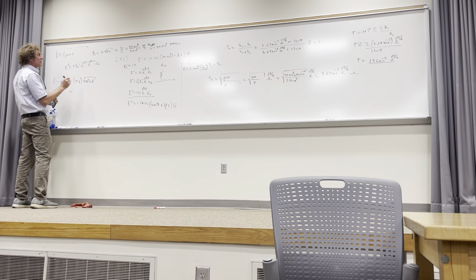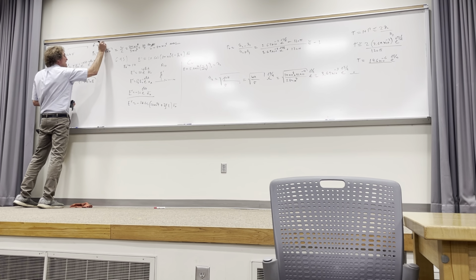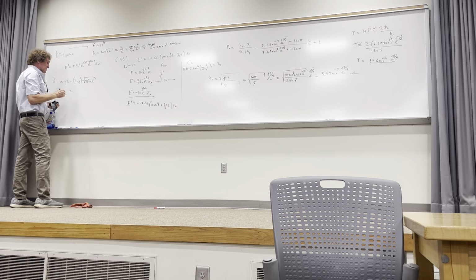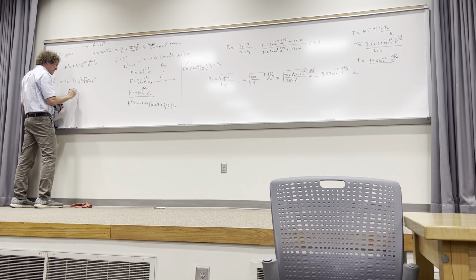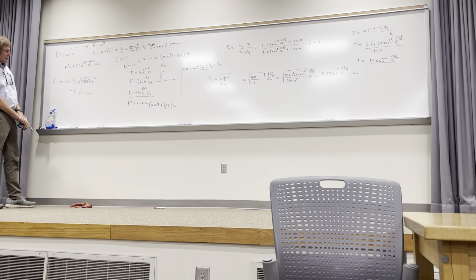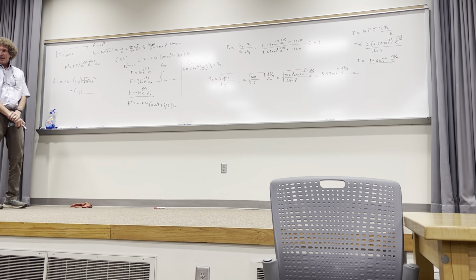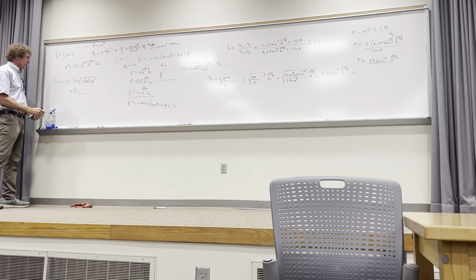Now, just for completeness, what is this value going to be? Do I have f here? I don't have f. By looking, what is f? Take a look. 10 to the 8th, right? And that's hertz. So if that's 10 to the 8th, can you punch the numbers on this one and tell me what it is? I'll leave it as 1 plus j times something. Just the square root of pi times 10 to the 8th times mu naught, which is 4 pi times 10 to the minus 7, times 5.8 times 10 to the 7. I'm just curious myself. And alpha will be beta, right? It's a good conductor. Alpha and beta will be the same.